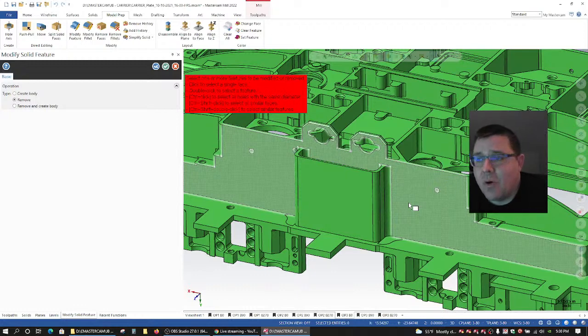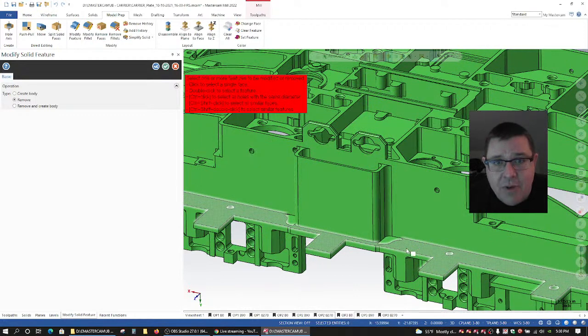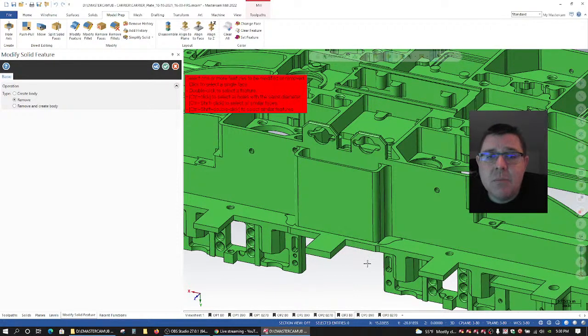One file for design and layout and setup sheet generation, maybe because it's got the more complex models, but then another file where you're doing manufacturing. I've had to have it where I've had kind of my op1 model, my op1 Mastercam file, my op2 Mastercam file, my op3 Mastercam file, and I don't like to do that, but sometimes it just becomes the nature of the beast when dealing with hundreds of megabytes of data and toolpaths.